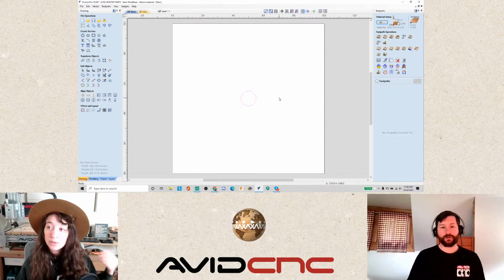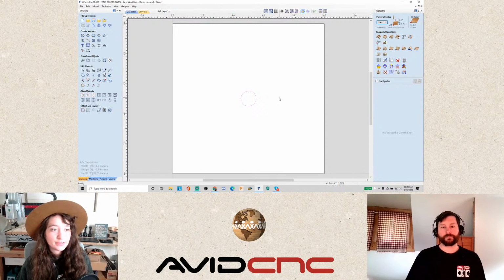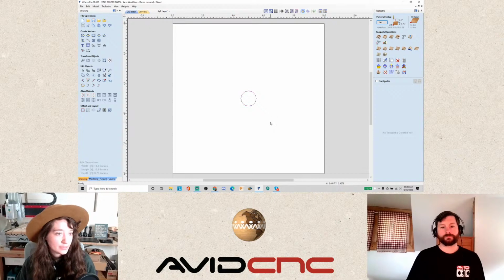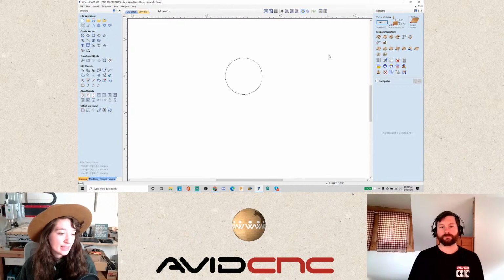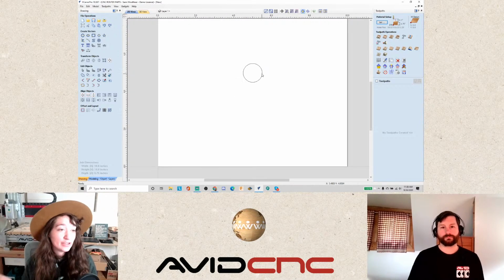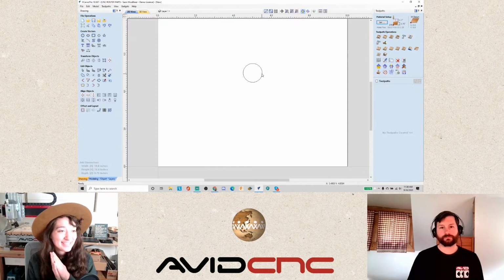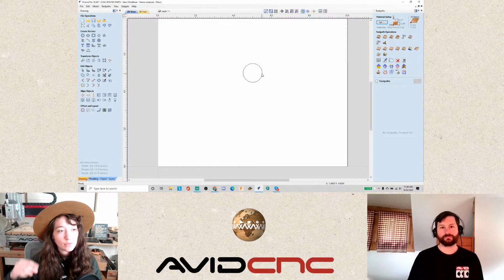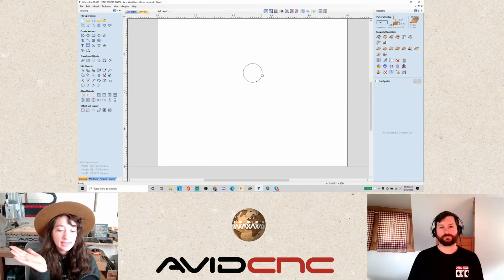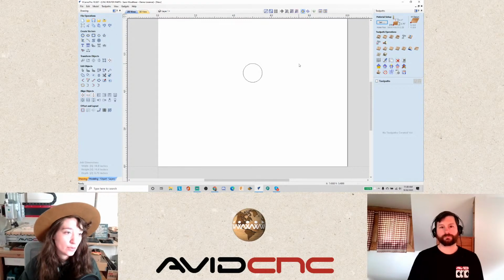Right, and so I think we're about to go into also talking about the chamfer toolpath as well. So I'm just going to give a short example of that here. As an alternative to doing a counterbore, there's the countersink, which is a perfectly nice bevel for your screw head to sit in, making sure to accommodate for the angle of the screw head, knowing what that angle is, and making sure that your router bit matches.